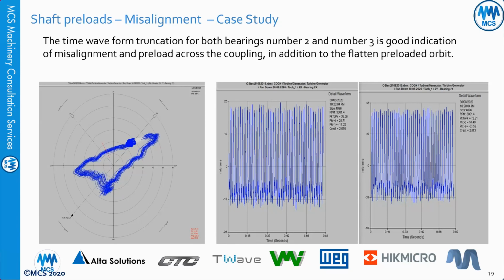Normally the load affects it. A very common thing in generators is called thermal imbalance, so this definitely increases because of that. You might have the preload, which is the misalignment, or you have a secondary damage, which is the rubbing. Rubbing is considered a secondary damage, happening because of unbalance, runout, eccentricity or shaft preload.